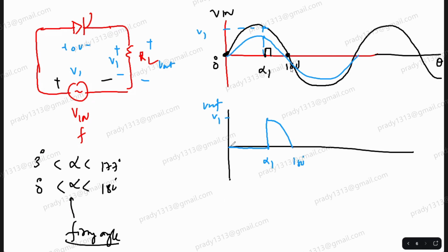Is it correct? Yes, sir. Because the moment you stop the gate current, it still remains latched. This we discussed, that even if you make the gate current 0, the device is latched and will keep conducting till it is reverse bias, right?